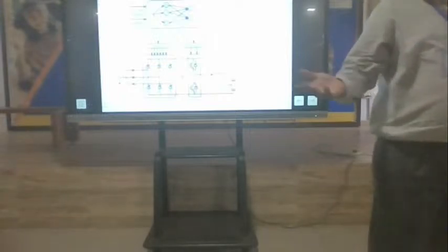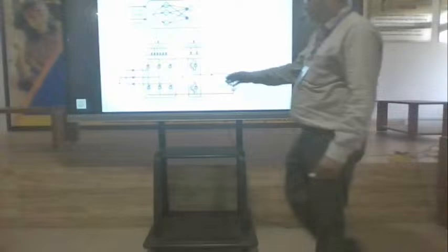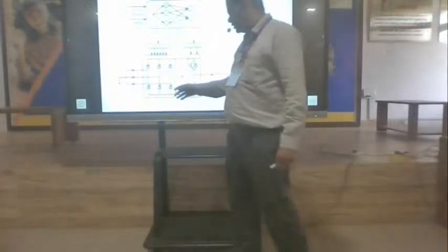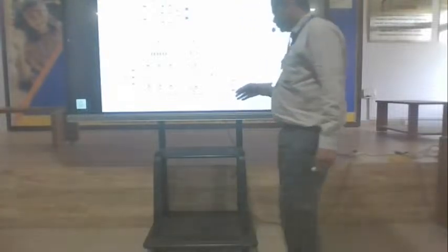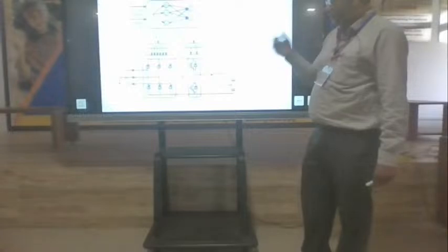While charging the battery, you will be giving current to the battery. Similarly, while taking the power supply from the battery, the current flows in the opposite direction. So this converter setup is a bidirectional converter, where current flows in both directions. We will have high frequency MOSFETs. While charging, in the regenerative mode, you can give the supply from the generator.